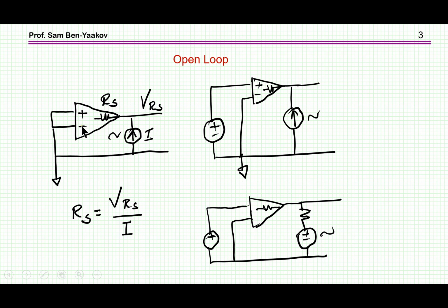Because of the offset, the amplifier will immediately get into saturation. In fact, you cannot do it in simulation either, because most models will also have some offset. In simulation, you can adjust the input to have a proper operating point.